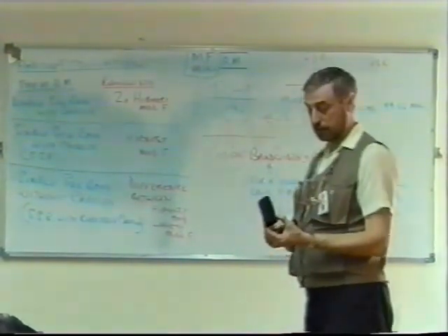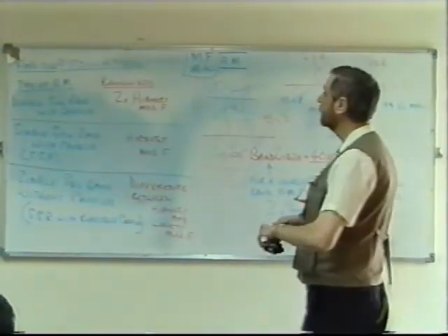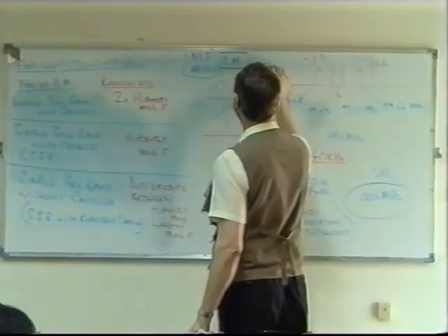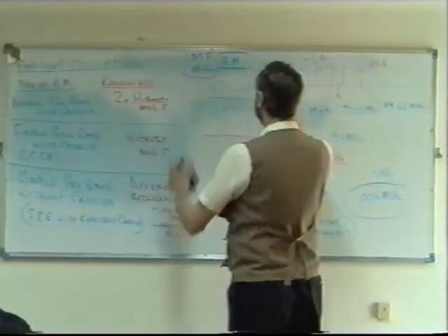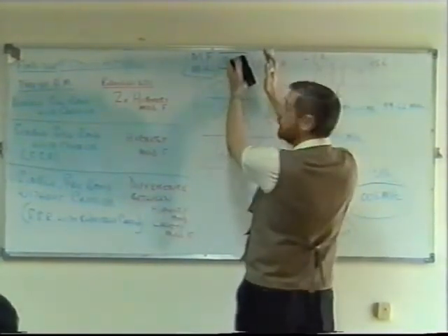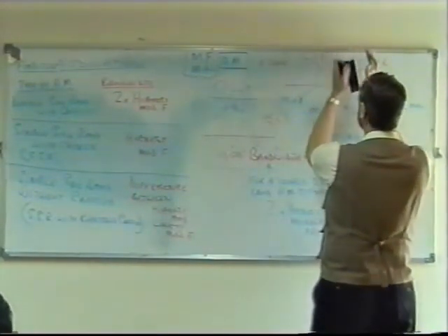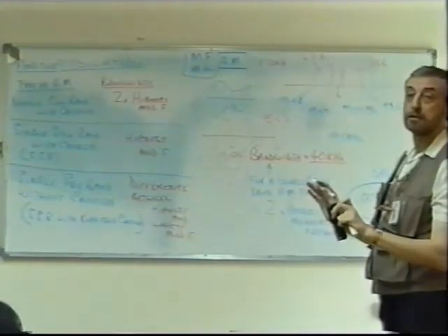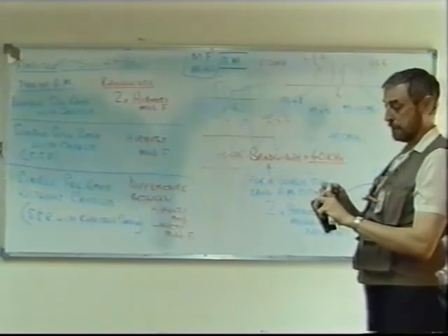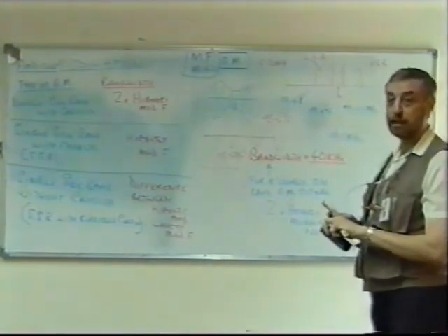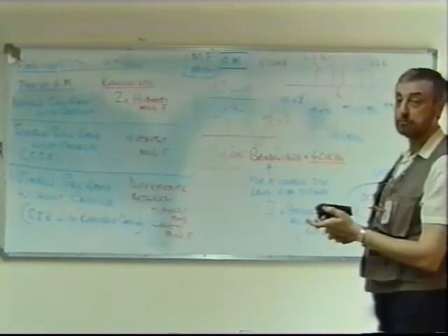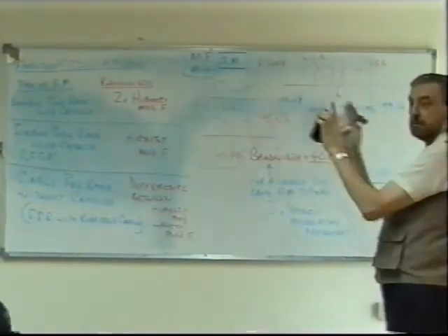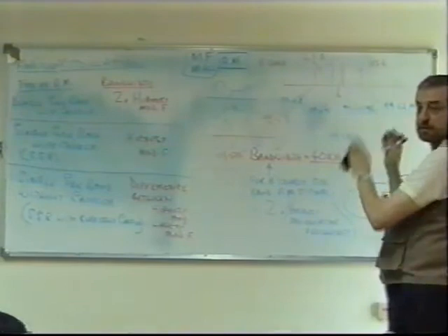Basically, if you consider your modulating frequency to be between 5 and 20 kilohertz, all you're doing is taking those frequencies and shifting them to that position on the frequency spectrum. That's all you're doing with suppressed carrier modulation. It's like taking the same band of frequencies but moving them up to your radio frequency band.